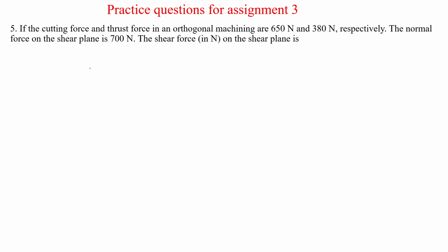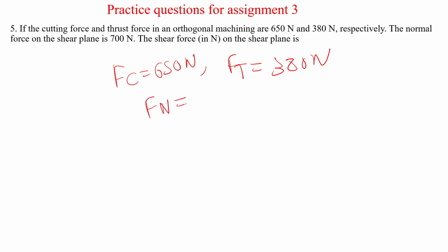Now it is given the cutting force and thrust force. Fc is 650 Newton and Ft is 380 Newton. The normal force on the shear plane, Fn, is given as 700 Newton. The shear force on the shear plane is Fs and the normal force is Fn. Find the shear force Fs. Can you do this? Please do this.